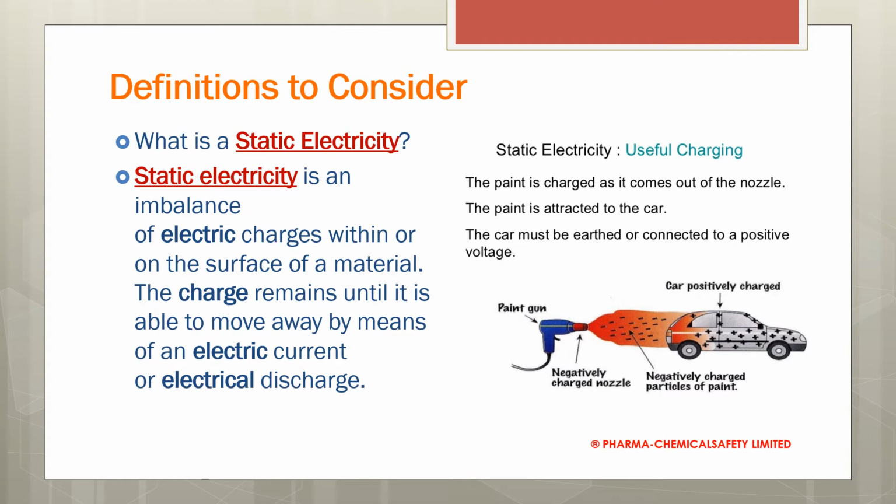Some of the regulations in OSHA, the flammable and combustible liquid regulation, mention that standard as well, along with NFPA 30 and NFPA 77, and in Canada, if I remember correctly, as well. So there are good practices there to dissipate static electricity while handling these types of liquids.